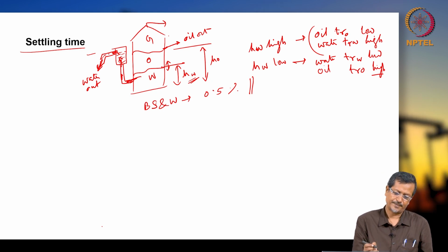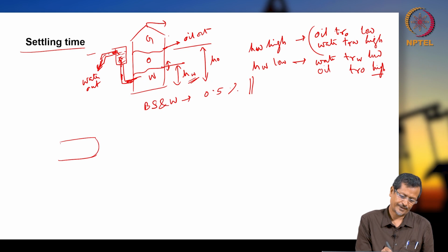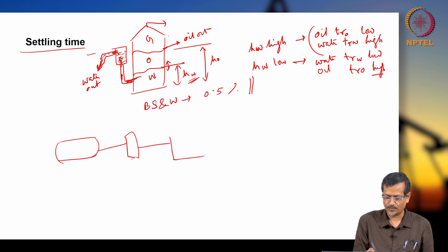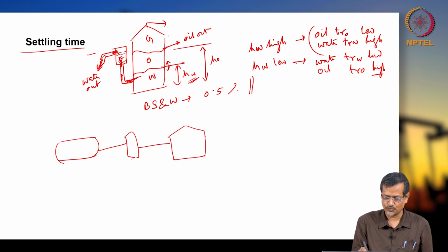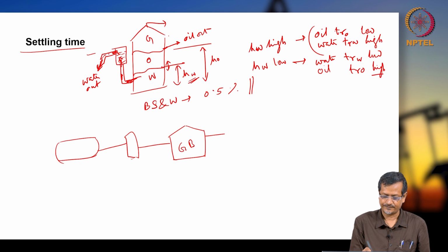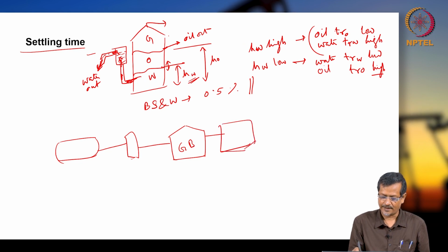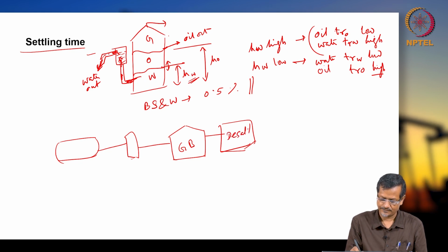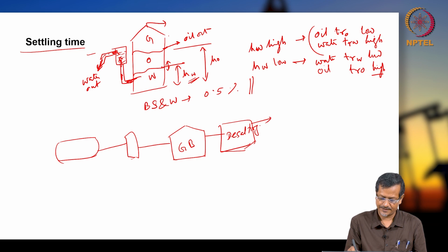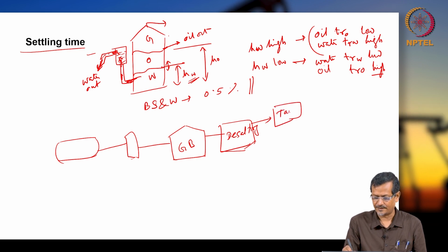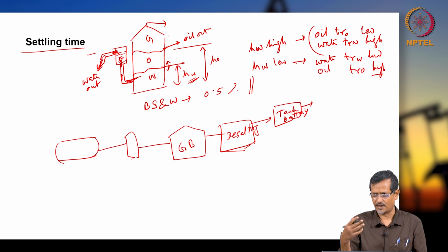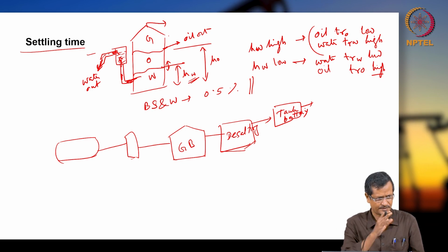Normally, from the well bore you get one separator, then another separator, maybe vertical, maybe horizontal, then almost before the settling storage tank battery, the gun barrel. There may be another arrangement called desalting, then your tank battery, or in the offshore case an FPSO or other mechanism we can use to transfer oil from the separator systems.